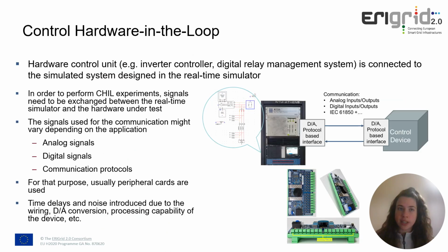The rest of the presentation will focus on the control hardware in the loop method. As we have already discussed, this method concerns the interfacing with the real-time simulation of inverter controllers, digital relays, central controllers, etc. In order to perform control hardware in the loop experiments, signals need to be exchanged between the real-time simulator and the hardware under test.